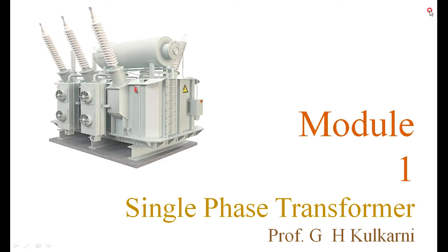Continuation with the equivalent circuit diagram of a transformer. In this particular session, we'll see how to draw the vector diagram and do the calculations for the simplified equivalent circuit diagram referred to the primary side. We will recall once again the equivalent circuit diagram of the transformer referred to the primary side.